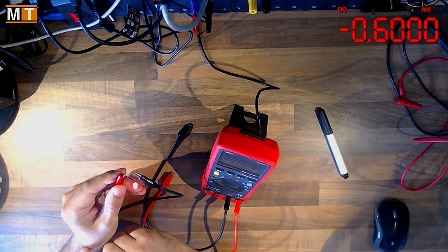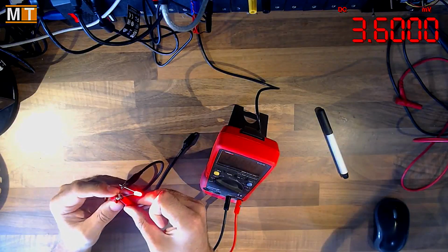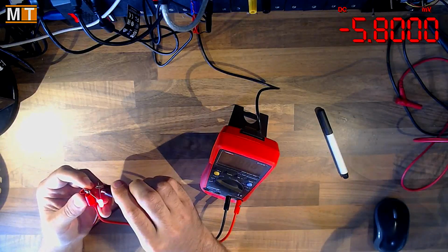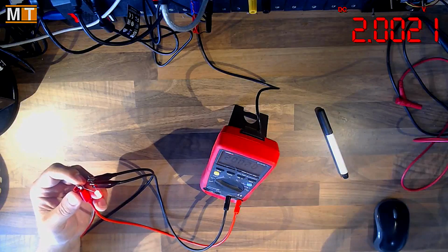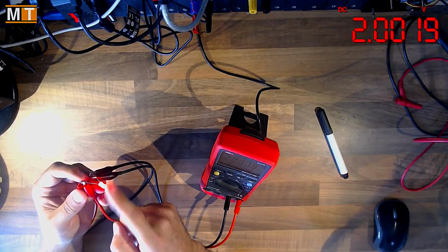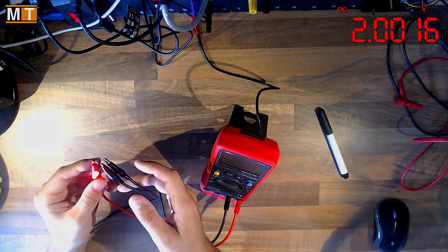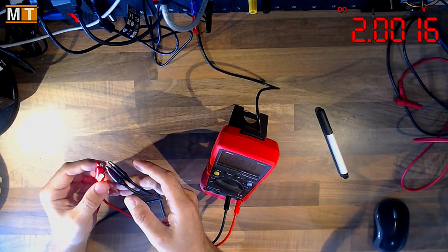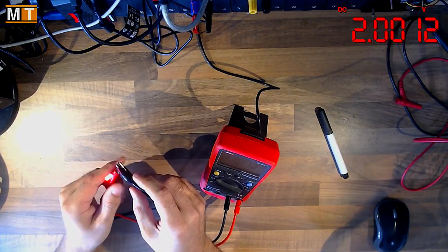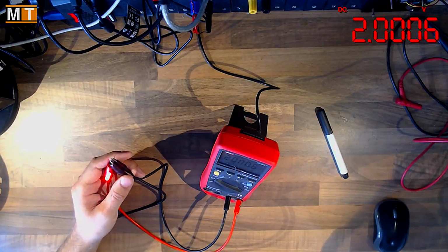It lights up perfectly. And the voltage across the power supply has been limited to 2 volts. At 20 milliamps, the forward voltage of this LED is 2 volts almost exactly. So regardless of what voltage you provide, as long as the current is limited, the voltage will be clamped by the LED to the correct voltage.